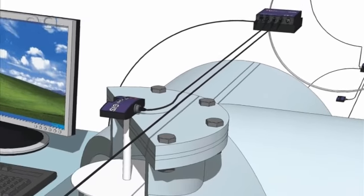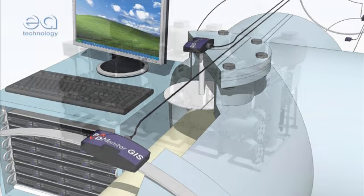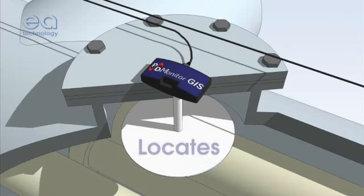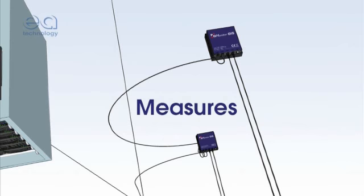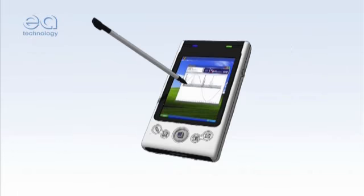We've also developed a specialist monitoring and alarm system for extra high-voltage gas-insulated switchgear, the PD Monitor GIS. This is specifically engineered to detect, locate, identify and monitor the 5 different types of PD activity that affect GIS assets, to warn when PD activity reaches critical levels and prevent faults developing into failures.